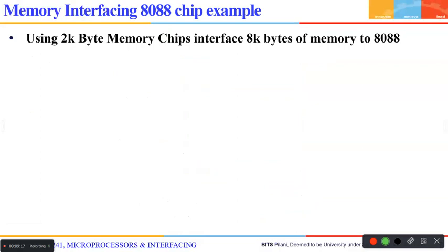There is a technique called even and odd addressing. Even and odd addressing, okay? You remember the Chief Minister of Delhi when you say even and odd? I don't know how many of you remember. But this is not that even and odd. This is something different. Even though the memory chip gives you only 8 bits at a time, the microprocessor will use 2 memory chips at a time, like 16 bits. That's what the fun is.